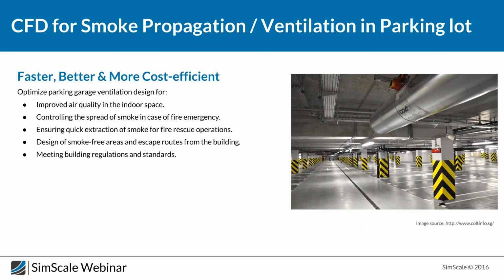So let's assume if something goes wrong, if one of the electronic components catches on fire, the design of the parking garage should be in a way to be able to handle this situation very easily. So the smoke and the heat should be removed from this closed space. Also, certain areas must be provided for the people who are inside the garage to leave this space and go to safety.